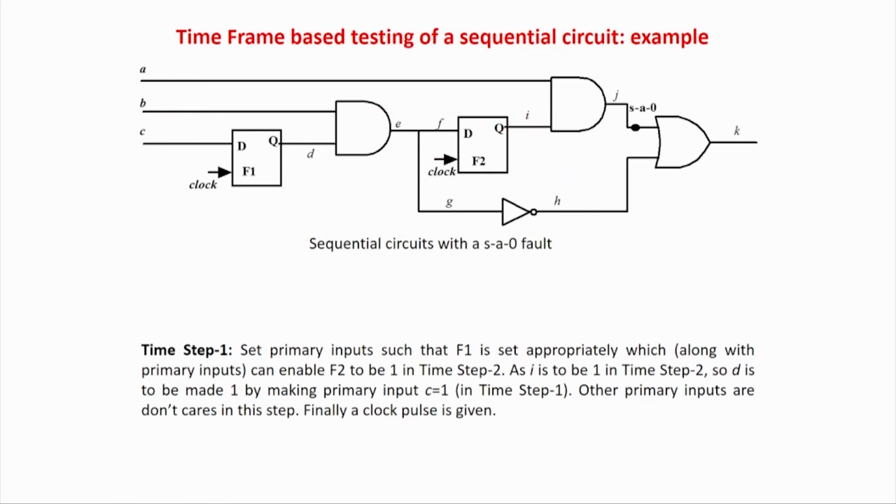So, test pattern generation did not do any kind of backtrack etc. Directly it can say that okay, I can make this pattern a 1. So test pattern generation time is highly optimized if you are using a scan chain, but test application time is not solved. Because if there is a scan chain whose length is say 10,000, that means, for example, if some of the flip flops are at the depth of level 1000, the scan chain length also will be 1000, because there is a flip flop whose depth is 1000 from the primary input to the primary output.